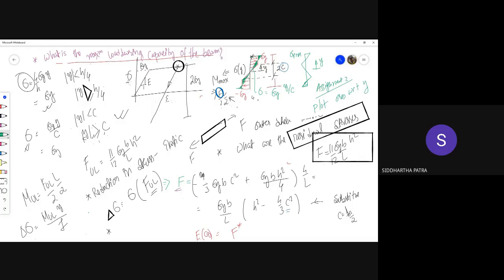Now, your argument should be, how can the stress on the material go beyond sigma y? The answer is, it is actually not. We are simply considering from plus sigma y to, you see the elastic window while unloading is of twice sigma y. It can go from plus sigma y to minus sigma y. It's with respect to this plus sigma y that I am considering developing a stress. I'm actually considering the unloading.